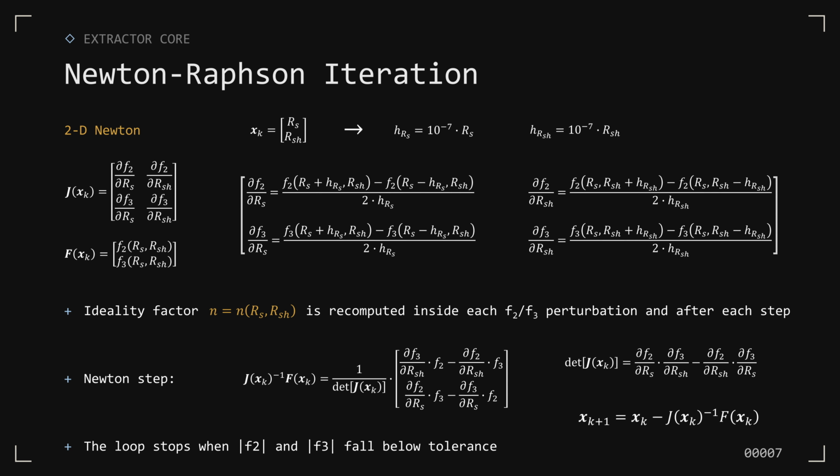The chosen tolerance is a small number near 0, at a point where each iteration is barely changing the unknowns or the result of the residuals. I usually define it as a constant in Python, and you can do a little bit of trial and error to see what works best. Even with all of those calls to recompute the residuals and the ideality factor, the solver is fast and usually converges in just a few iterations. We're almost home, but we need one other solver tweak to ensure consistent convergence, which is to bound the Newton step.